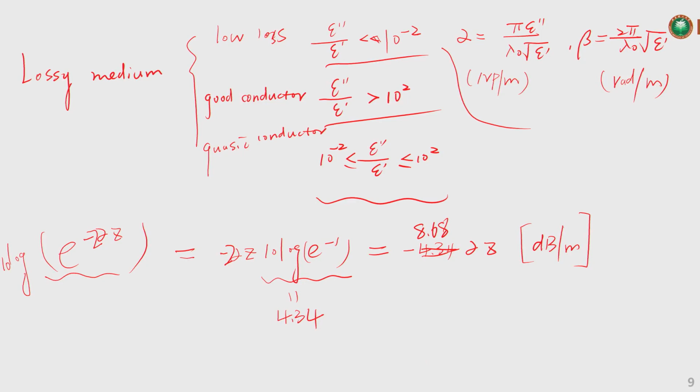So if you read code, sometimes from others, you can find that when we get the attenuation constant and calculate the power loss, there is the parameter 8.68. You should know that it's because it's converted from the linear scale to the logarithmic scale. So it becomes like this one. Here alpha is the attenuation constant of the signal or the channel, and then the propagation distance, maybe meters or maybe kilometers, something like that. Okay, this is for the low loss dielectric.